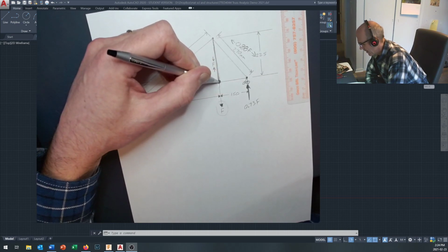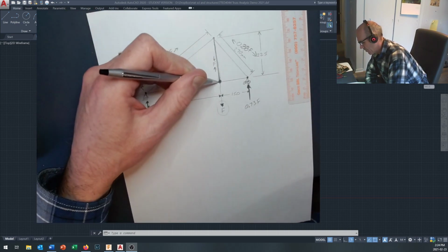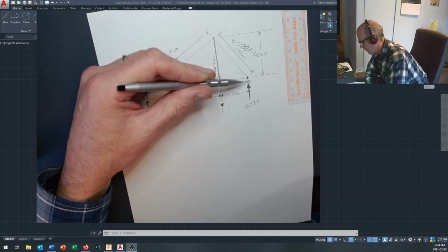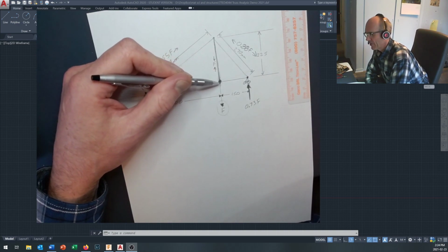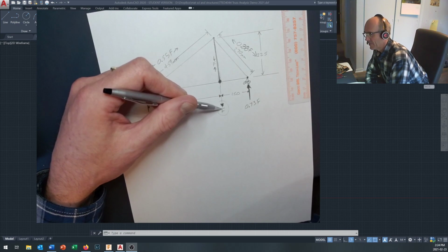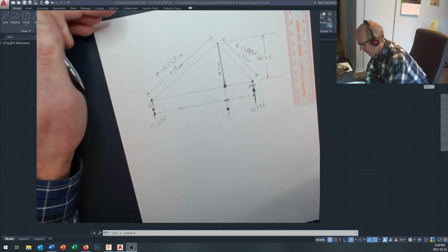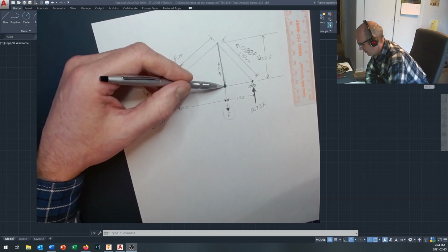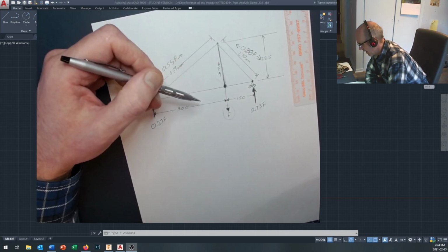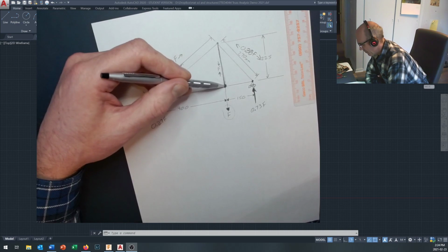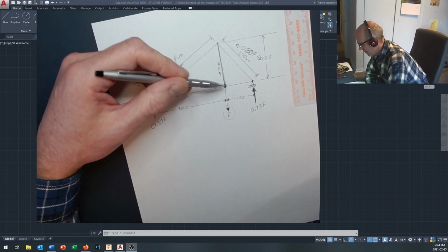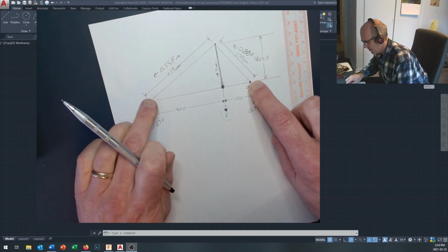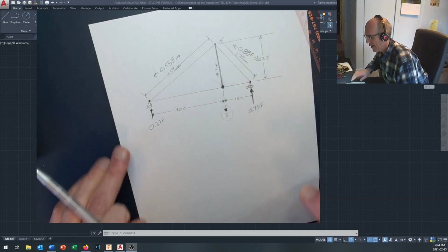This line is perfectly horizontal. This line is perfectly horizontal. They cannot provide the vertical support we need on here to resist any kind of substantial F down there. So it'd be very weak to build this without something. It could be coming up at an angle in here, but you need something holding this node up. These two right here are just holding these bottoms from popping out like that.